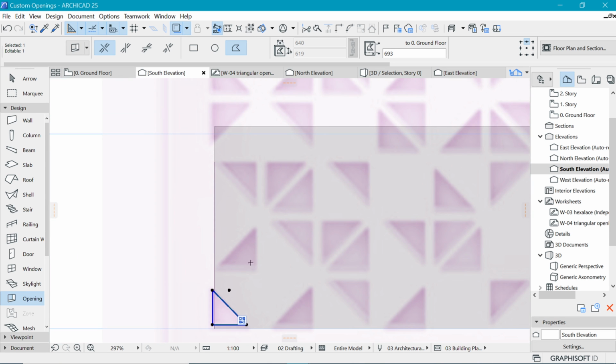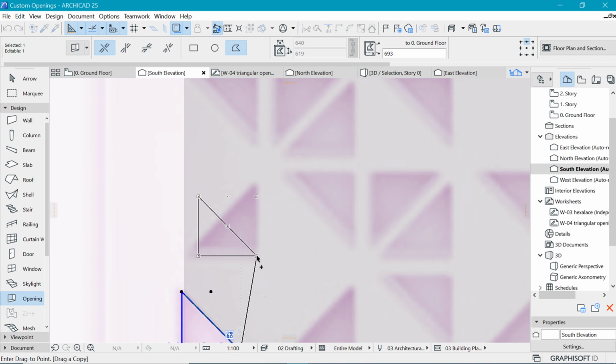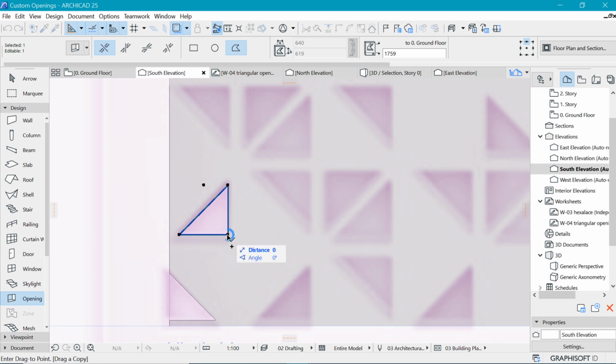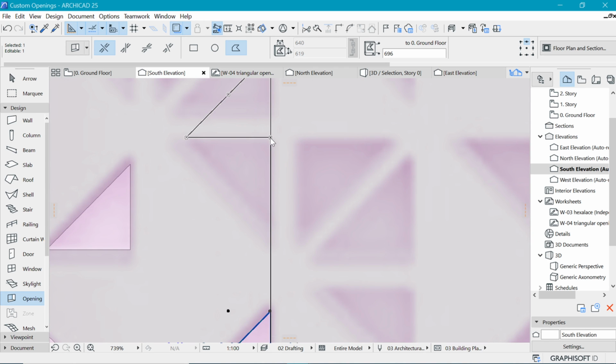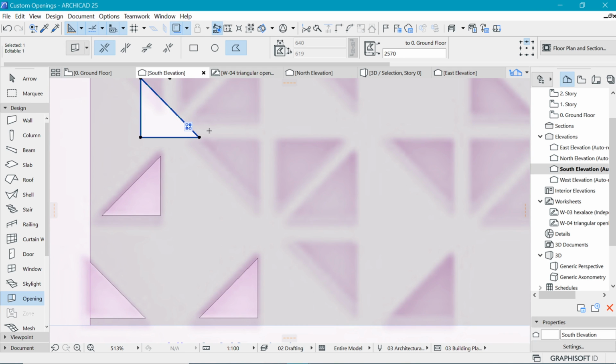It's very handy. To create a copy, all you have to do is to drag with Ctrl D and Ctrl again to have a plus, and be able to move this thing around, and Ctrl M to mirror and drag this thing into place. And that's all you need to know in order to create this. It's fairly simple and easy to work with, just that you have to put it either in floor plan or in 3D. It doesn't work in 2D for now, so be sure to note that.